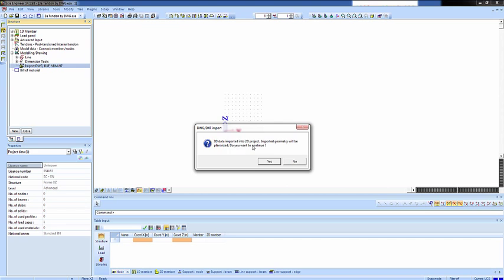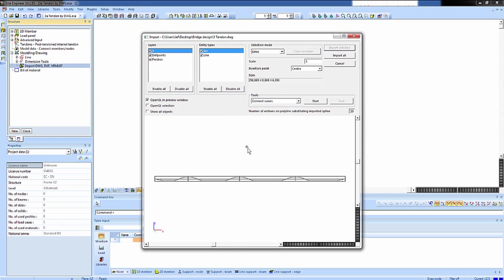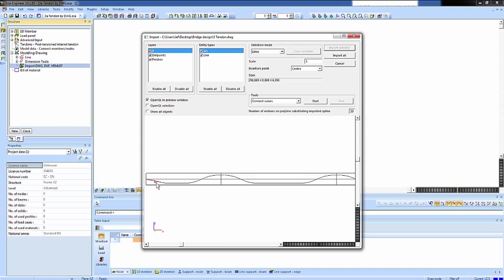Now this is a 3D file and I'm in a 2D project, so it will be planarized. Let's continue. Normally this file should provide the DWG or DXF with continuous polygons. Here it has not been provided.